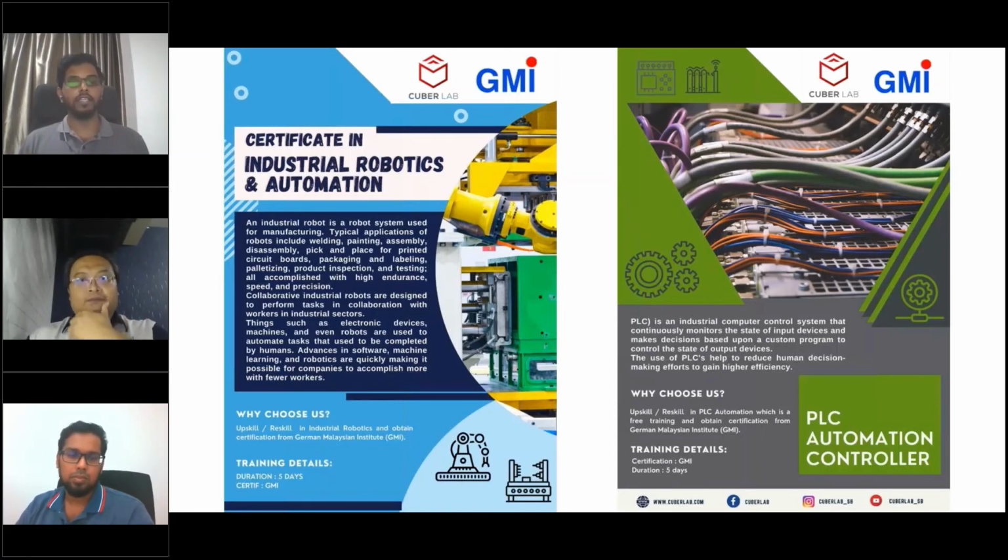In oil and gas, 6-axis industrial robots are also being applied, but the robot must come with a particular certification such as ATEX, which is explosion proof. This kind of application is still being implemented in oil and gas, but it depends on what kind of application they are looking at. It might be related to an oil and gas parts production facility, or really on an oil and gas platform.